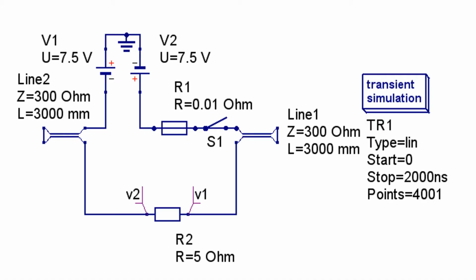The simple circuit in the video lends itself to transient analysis using readily available software tools. The size of the circuit dictates that distributed parameter analysis is the most appropriate choice, as opposed to lumped circuit analysis, as many of the commenters have used. Distributed parameter analysis models the long lines as transmission lines.